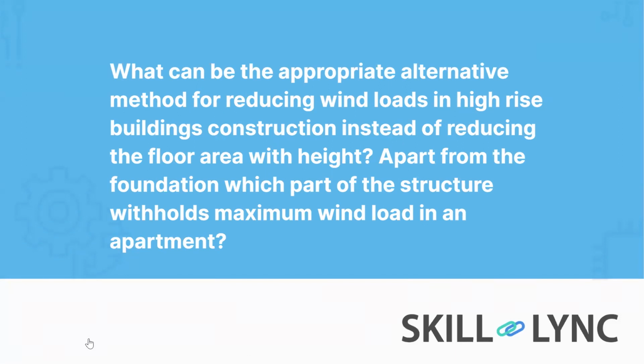This is one of my favorite aspects of designing high-rise buildings. Like I did explain this briefly before, but I'll just explain again here for somebody who joined late. See, for a high-rise building, the wind loads are the most critical of all the loads. The higher you go, more than the seismic load, the wind load plays a bigger part. There are two reasons for it.